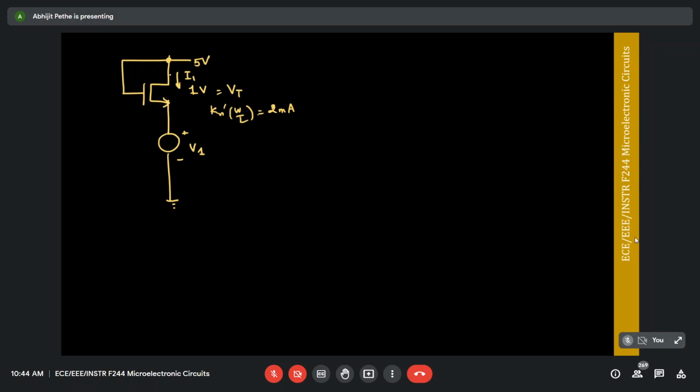So first of all, all of you should be convinced that this transistor is always in saturation. Whenever you tie the gate and drain together, that is when you make VGD 0, when VGD is 0, then the transistor is in saturation, right? And the reason why we call this the drain and not this the drain is because the voltage is higher at this end.